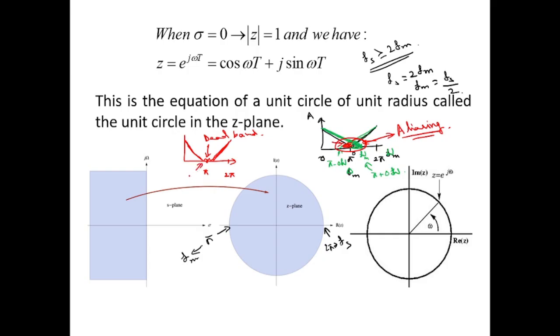So somewhere over here we will have the maximum frequency fm, and somewhere over here, there will be a region where there are no frequency components, and from there the DC frequency will start at pi. Suppose this is delta omega, so pi minus delta omega, and over here we will have pi plus delta omega. So this 2 delta omega region is called the dead band.